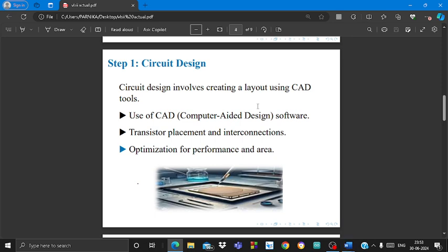It also converts the digital design into a netlist, a list of gates and connections. Placement: after doing all this, it determines the optimal placements of gates and components on the chip. Then connecting the components using wires, taking into account timing, area, and power constraints.